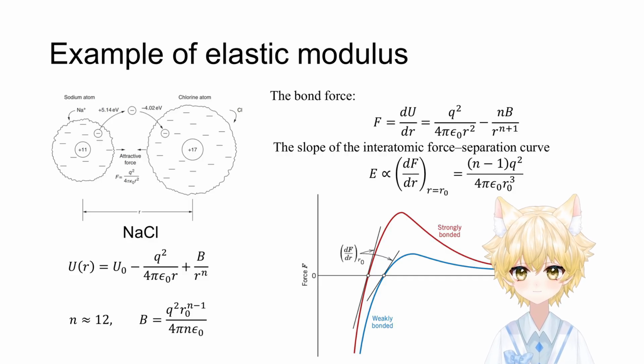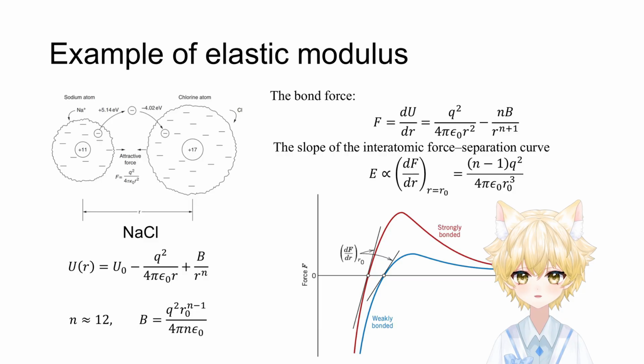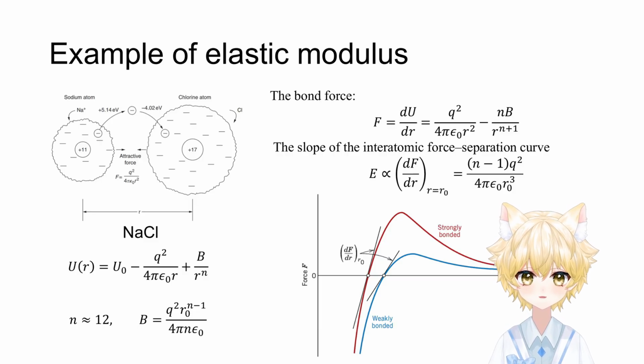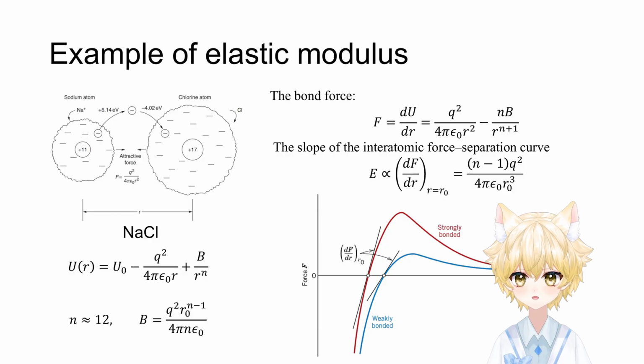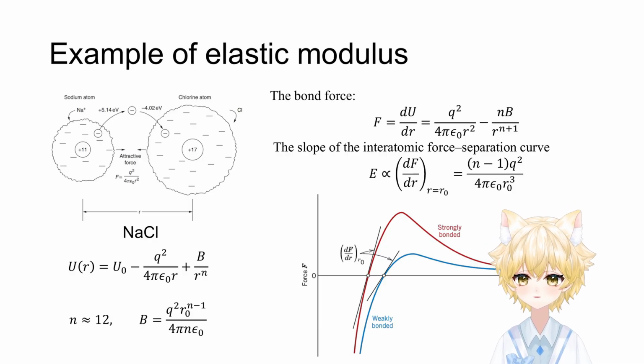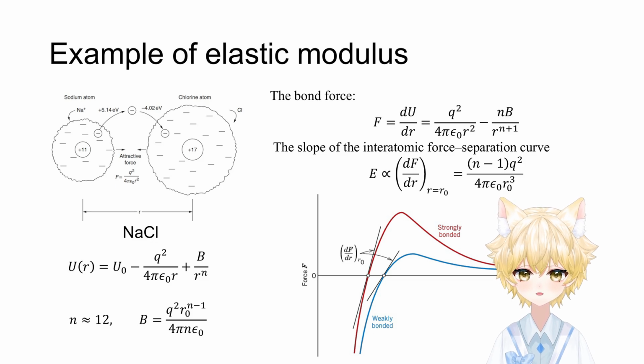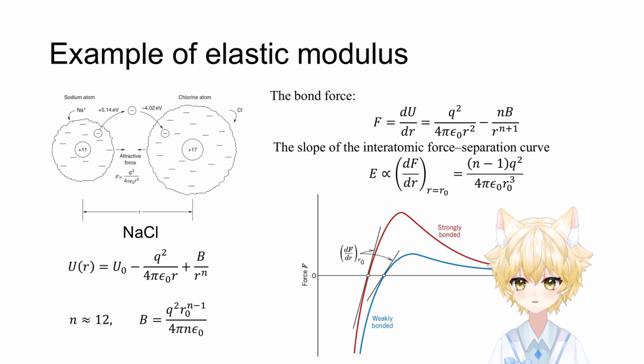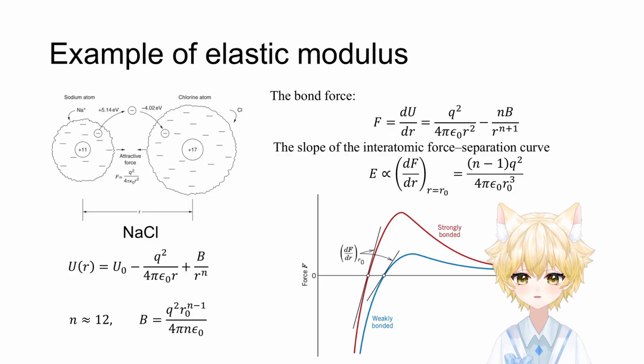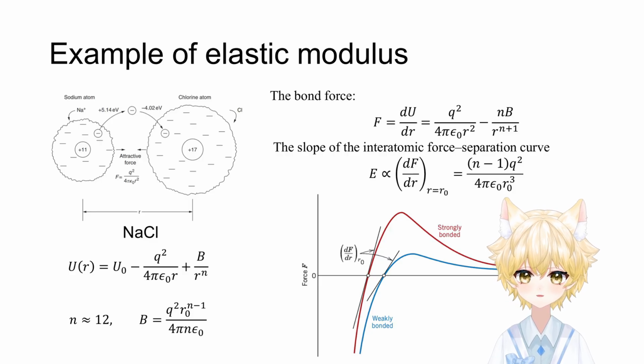On an atomic scale, macroscopic elastic strain is manifested as small changes in the interatomic spacing and the stretching of interatomic bonds. As a consequence, the magnitude of the elastic modulus is a measure of the resistance to separation of adjacent atoms, that is, the interatomic bonding forces.